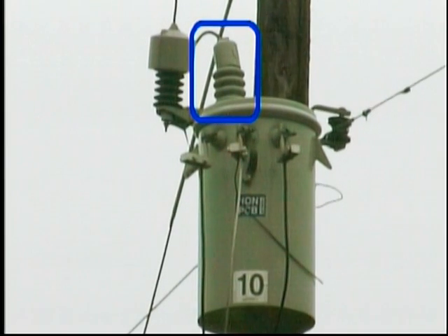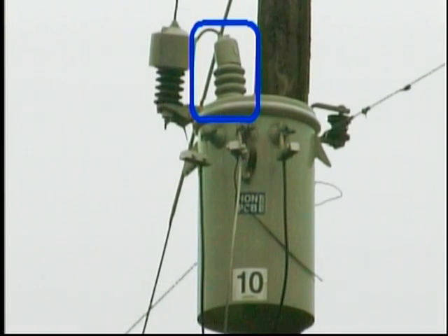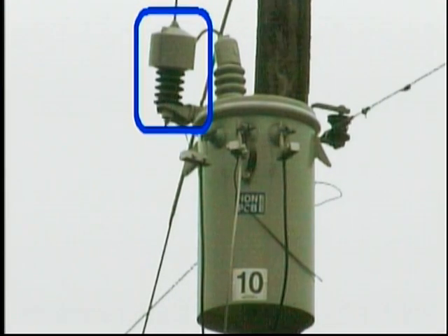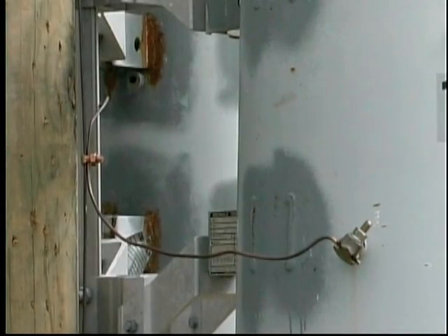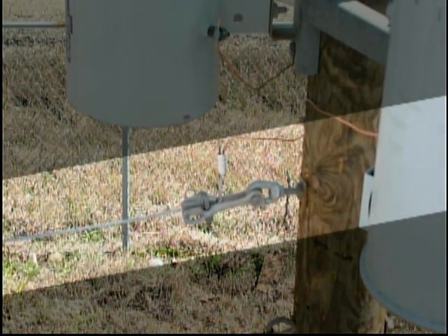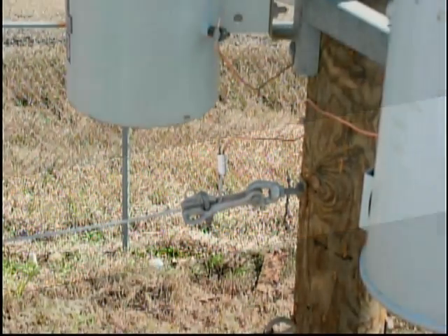The bushing is insulated for a specific primary voltage and serves as a connection point between one end of the primary winding and an energized phase. In this example, a surge arrestor is also mounted on the housing to protect the transformer from damage caused by voltage surges. The other end of the primary winding is connected to a case ground located on the side of the transformer housing. The case ground is used to connect the transformer to a grounded system neutral.